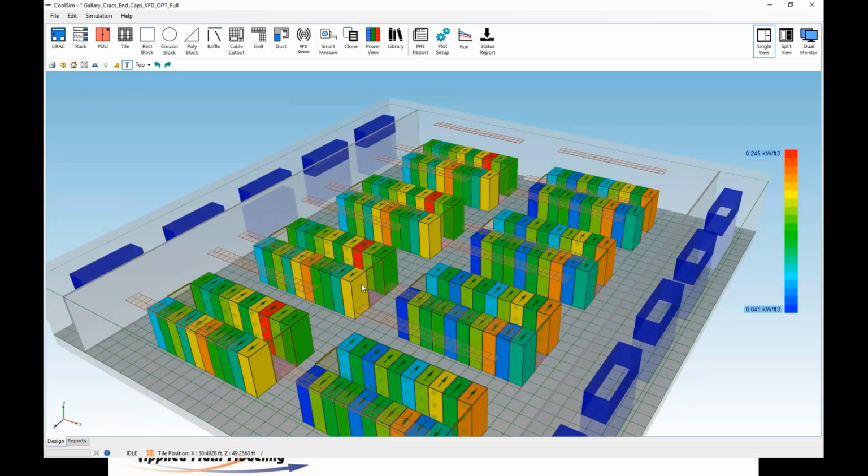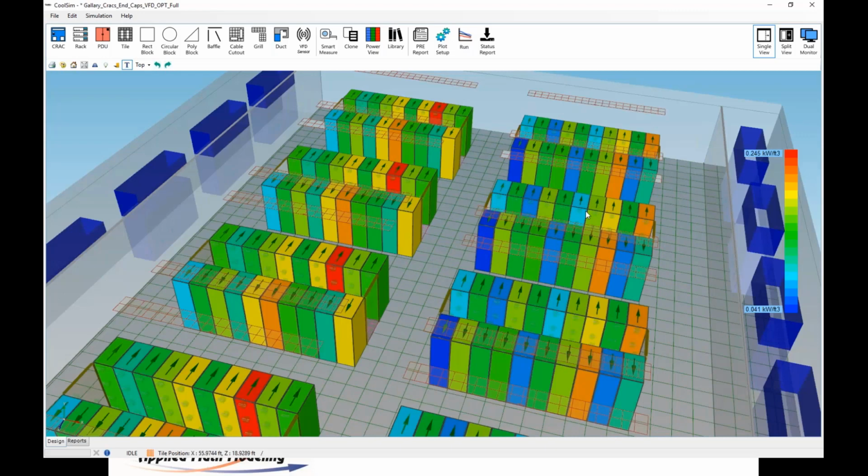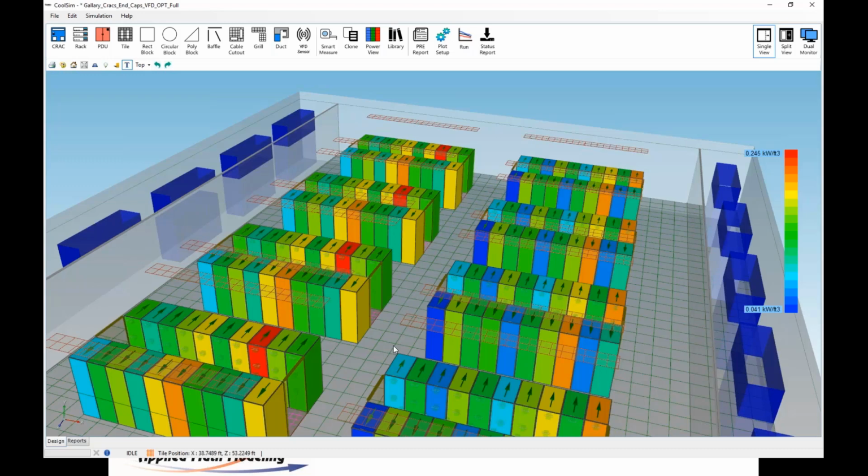And you see here that in some areas I'm more heavy than others, and I tried to uniformly distribute the load around the room. So it is assuming that the racks are operating fairly perfectly with respect to leakage. So there's no leakage assumed in this model through those racks at the moment. You can always add it, but I did not assume it here because I'm trying to make another point.